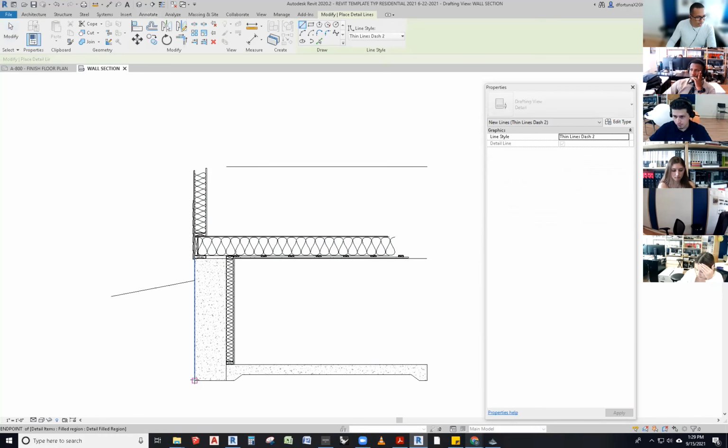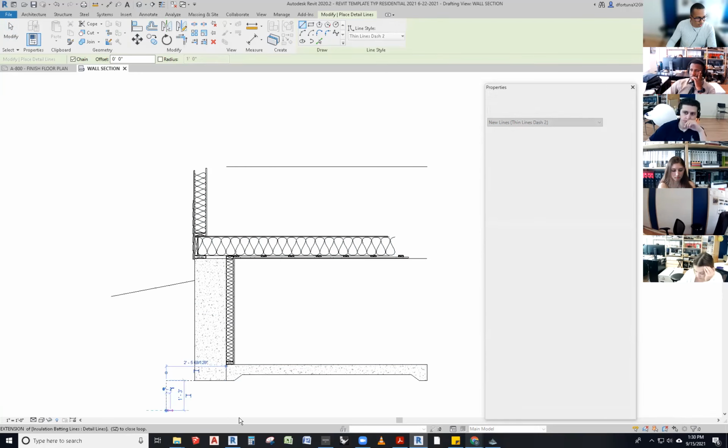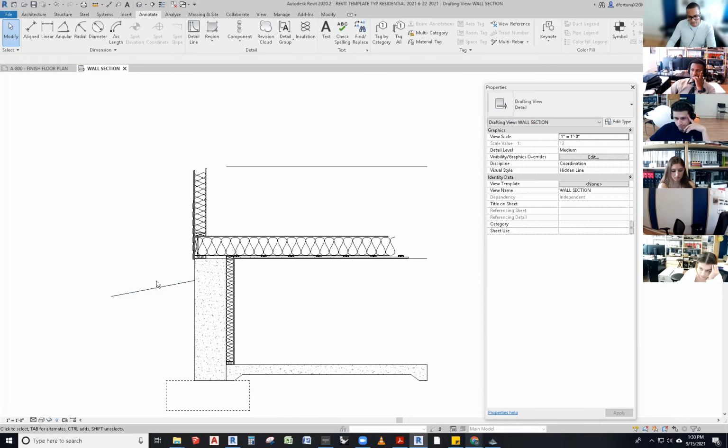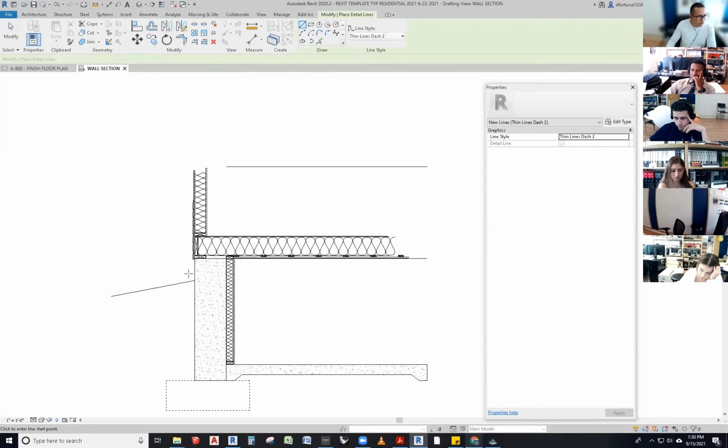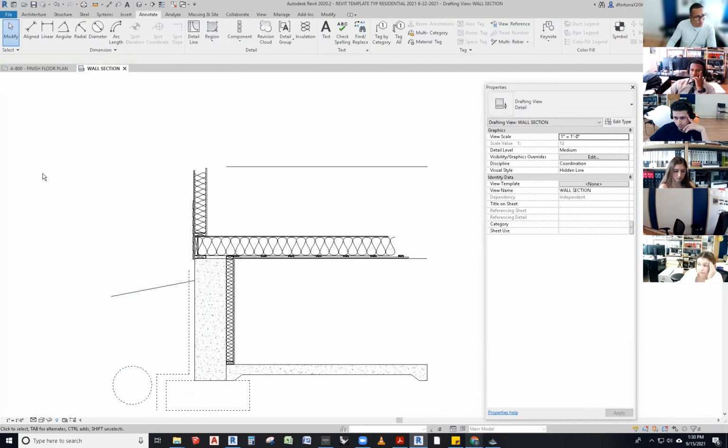From here on, you have your foundation, right? You have your dirt, you have an air and vapor barrier outside. We can go on and on with this stuff, right? We can have a little French drain right here for water purposes, so that water hits this and goes into this pipe and doesn't create a lot of hydrostatic pressure.